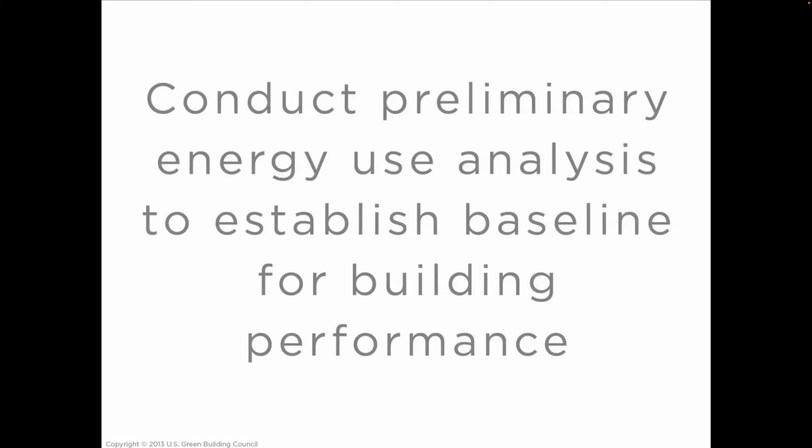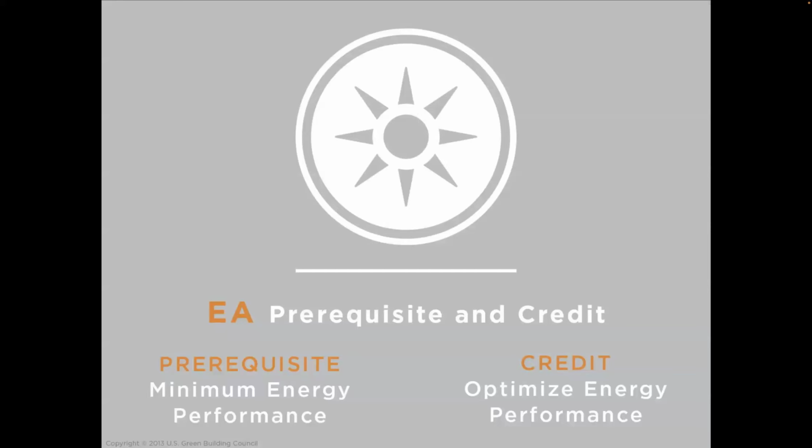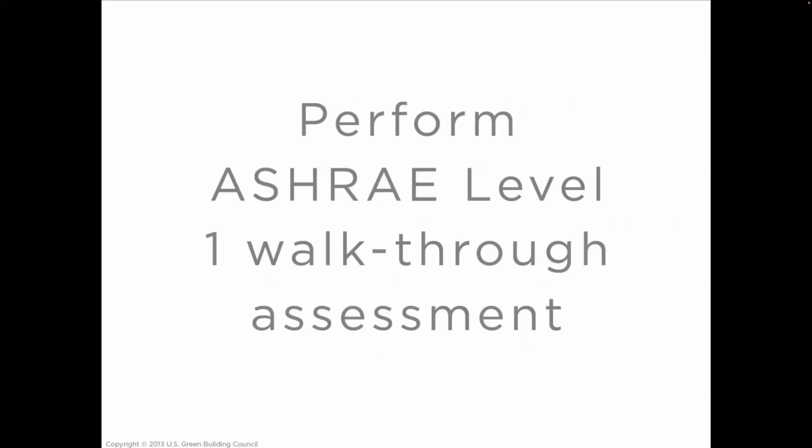And that's because you can have all the best systems, but unless you actually have performance data and you understand what it is, you can't do anything about it. You do the walkthrough, walking through all the spaces in the building. And we will have more slides on what you need in it, but ultimately you're looking for some no-cost energy savings. For instance, could we change to LEDs? Can we have occupant education where people turn off lights on their own? Those kinds of things. And then you also outline capital improvements.